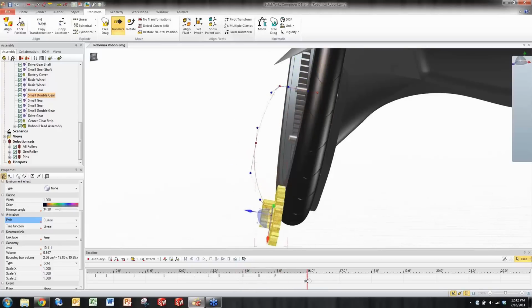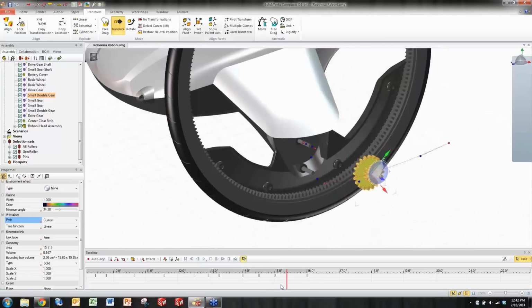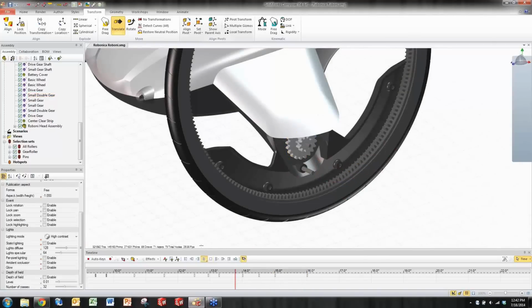Now I'm going to turn camera play mode back on, and I'm going to watch this thing from the angle of the camera. Basically play. And it's just, we can't really see it, but you were able to see how I was able to add a spline as a custom movement. This can allow for some very complex movement when disassembling parts within your assemblies.